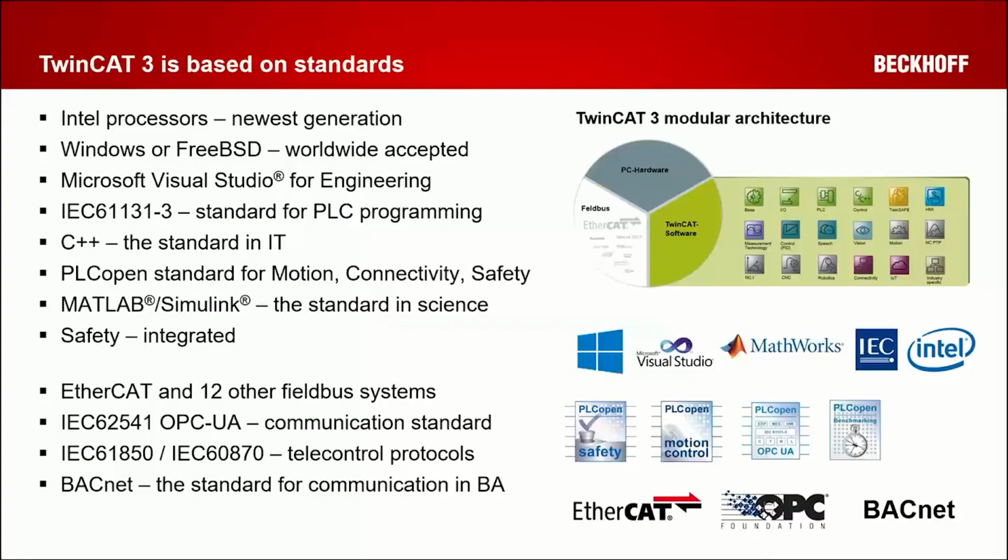To interface TwinCAT, we have a lot of open standards. As I already said, TwinCAT 3 is open in the modular approach, but also by external interfaces. We have the basic Intel processors, basic operating system, Visual Studio for engineering and the programming interfaces, but also EtherCAT and all the other field buses like Profibus, Profinet, CANopen.